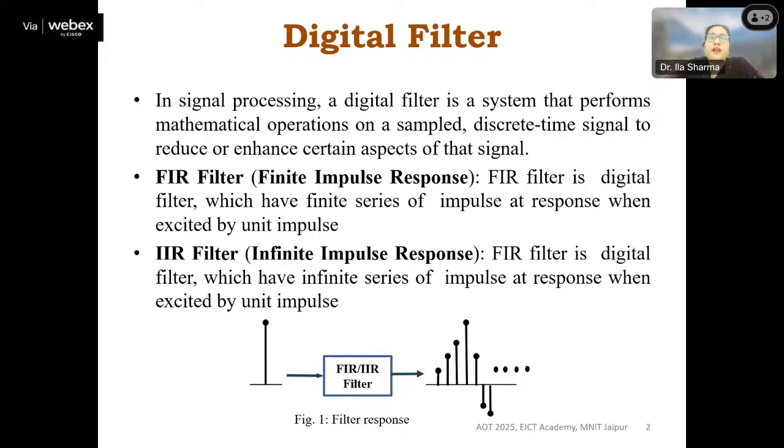For example, if we are dealing with frequencies which are low in nature, let's suppose we have some sinusoidal signal or some composite signal, but they have low frequency. We have to figure out how it can be amplified smoothly so that it can be given as input to another connected device. So definitely we have to use some low noise amplifier. What it is doing there is removing the noise component from the signal and then amplifying it.